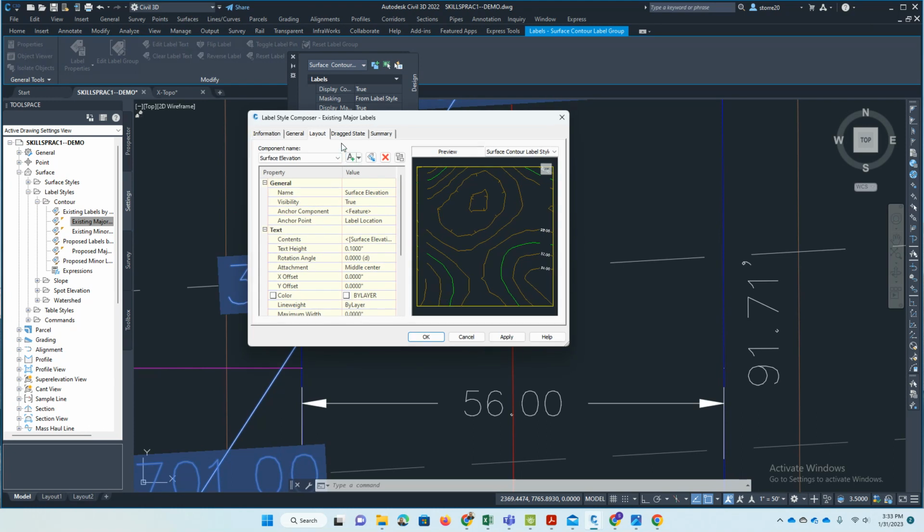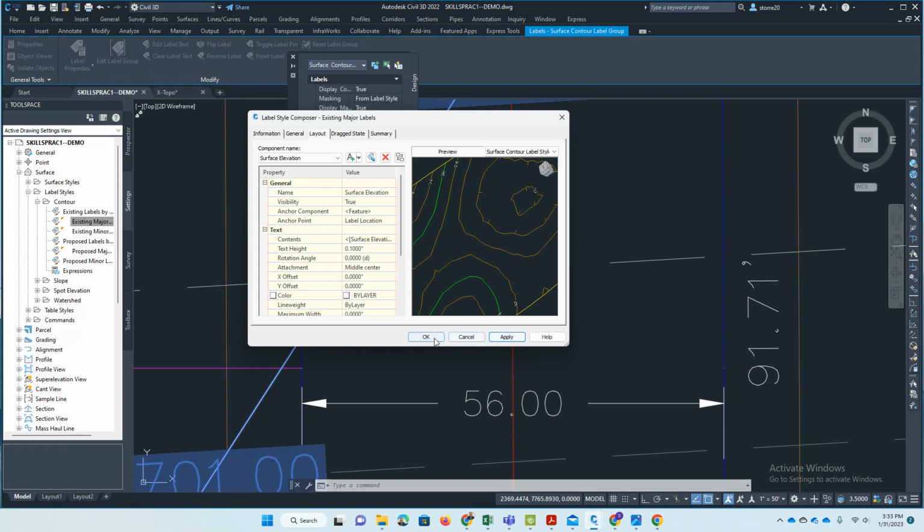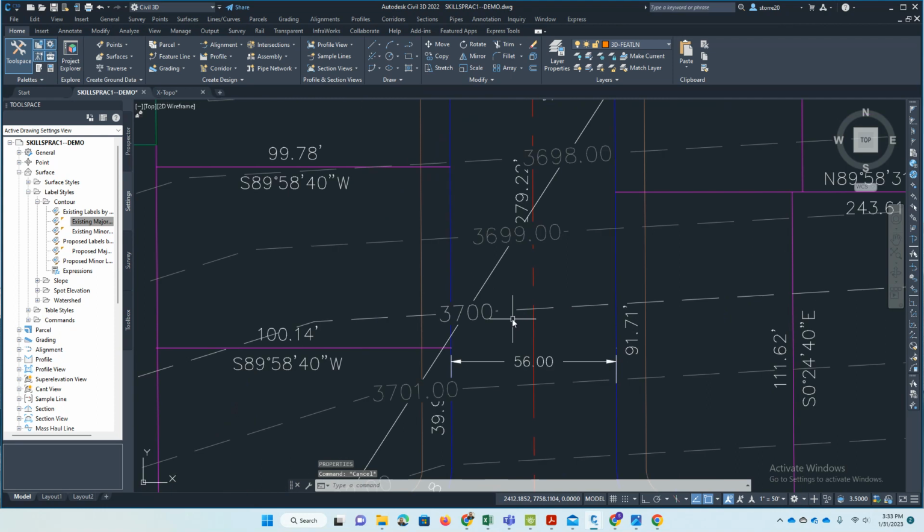Edit that one because right now it's showing us two decimal places. So we'd have to select this guy, and because you want to take that off, you usually don't show the two decimal places. Select the surface style, delete the little code, change that to be to the nearest one, reinsert the code, hit OK, and apply. That way we can just show it with no decimal places.